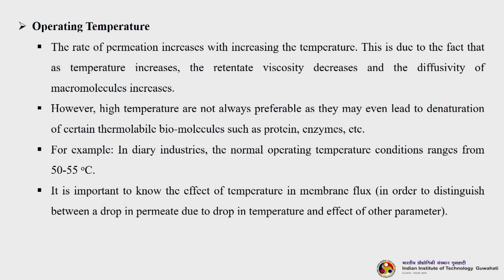Are you understanding? That means, when I am increasing the temperature inside the membrane module, the retentate which is getting retained on the surface of the membrane, of course, in a liquid medium, its viscosity decreases, because viscosity is a consequence of temperature. So, when the viscosity decreases, the diffusivity of the macromolecules inside the membrane is increasing. So, an increase in temperature up to a certain extent, of course, favors a high permeation rate.